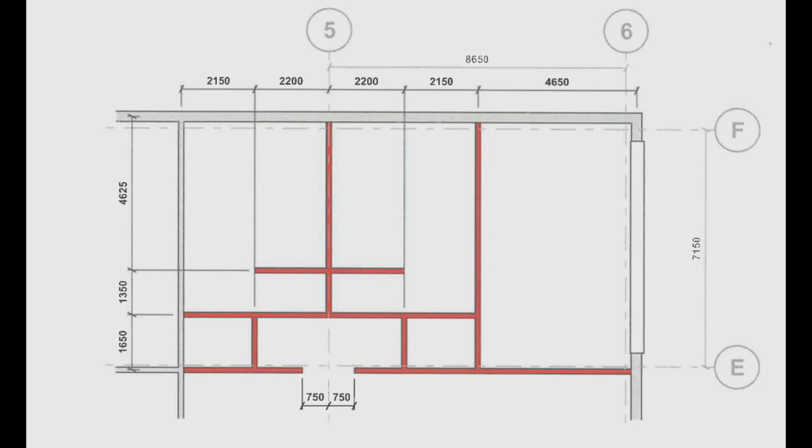And finally, we touch on an important feature introduced in recent versions of Revit, parts and assemblies, which allow walls, floors, roofs, and windows to be divided into separate pieces for tagging, filtering, scheduling, and exporting. We also highlight how Revit gives you the ability to add or modify the thermal properties of these building elements, allowing better integration with building performance analysis, heating and cooling load calculations, and GBXML workflows, which will be covered in future modules.